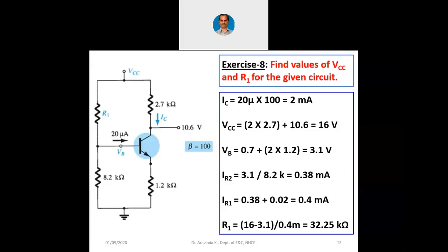Now please recall all the circuitry. You visualize all the circuitry. In all these circuits, always the input is at the base and the output is at the collector. So we are always measuring the input as well as output with respect to ground, and in general the emitter is common to base and collector.